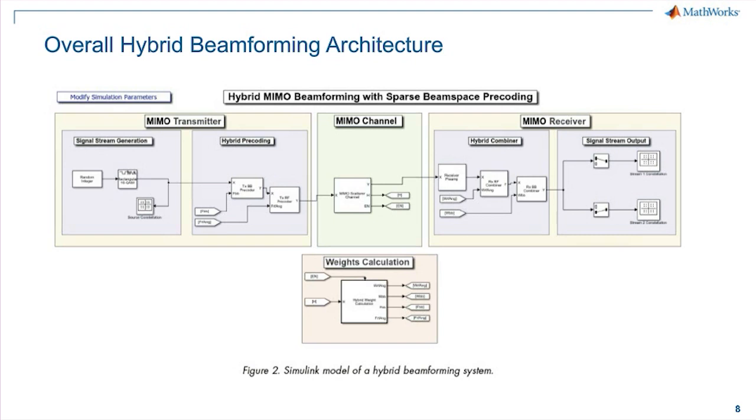And the key is that in the middle, the MIMO channel, if we get knowledge from the MIMO channel, we can actually compute all the weights, all those beamforming weights that have to be applied in the digital beamforming to each antenna port, and in the analog beamforming as phase shifts. We can derive them in the submodule, which actually derives them from MIMO channel characteristics.